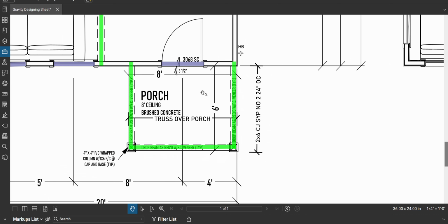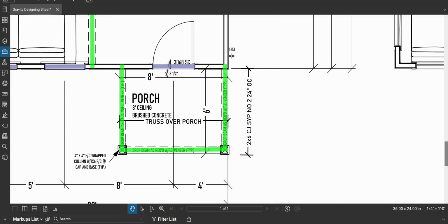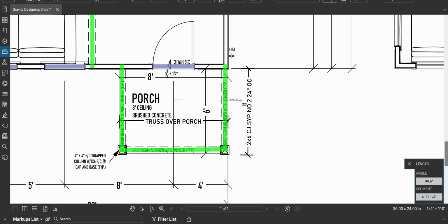So how much ceiling are we carrying? Let's deal with the ceiling first. The ceiling will be the center of this to the end of the ceiling, which is 4 feet, which makes sense because this is an 8-foot wide porch. So I'm holding 4 feet of ceiling. Okay.